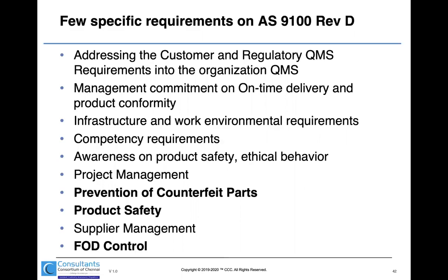And of course, if any supplier is dealing with critical items or key characteristics, your supplier does not have the authority to do any disposition on non-conforming product. Your supplier has to reach you. What do I need to do with this? I got a non-conformity. Am I authorized to do rework? Or can I scrap it as it is? Those decisions need to be taken by the engineering authority, mainly the designer. So these types of requirements we have to flow down to our suppliers where appropriate.